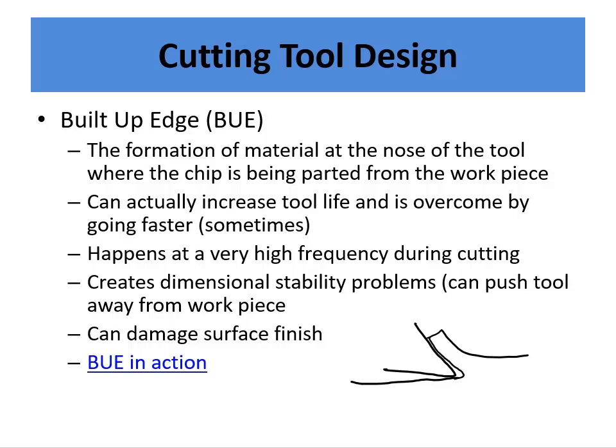And I think if you were looking carefully, you noticed that there was a little material that would get lodged here and kind of not move. This would all be sliding by, but this little ball of material would kind of sit, and then once in a while it would break away and move down here as the tool moves this way, the tool moves past it. That's called built up edge.